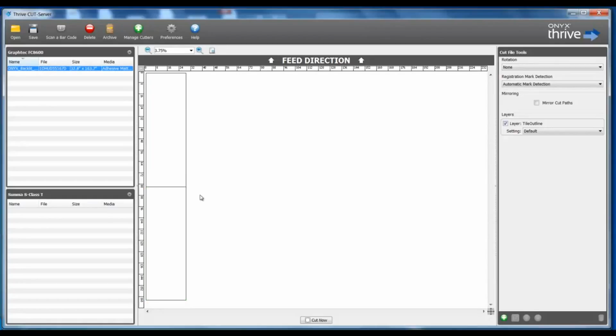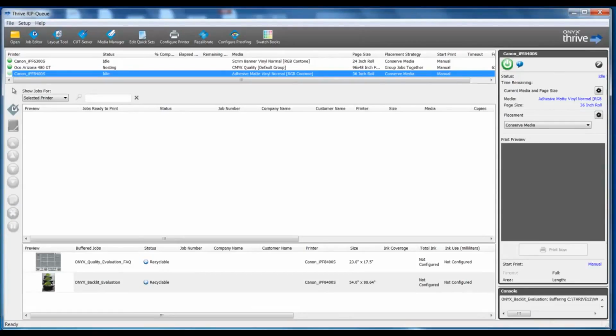At this point, I would take my print, go to my cutter, ensure my line up control points, and then at the very bottom, I would select Cut Now and send this cut information to the plotter to cut that little extra trim area around the tile outline. Our final output result will be an installable wall art job that is utilizing the cutter to do the tiling trimming.